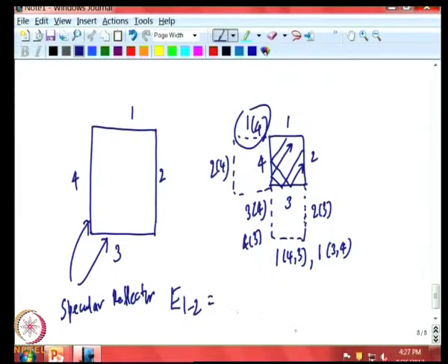Radiation leaving 1 and reaching 2 directly or through specular emission in 3 and 4. First term is easy to understand, F12, but after one specular reflection, it can come from image of 1 in 4 to 2. So, the reflected radiation here seems to come from the image of 1 in 4 right behind here. Okay.